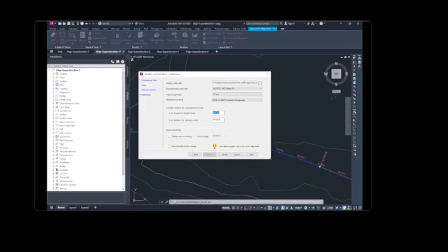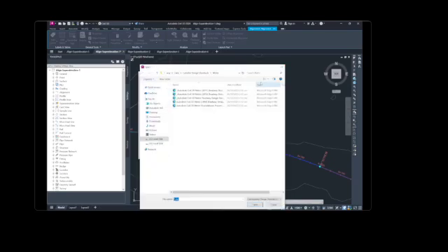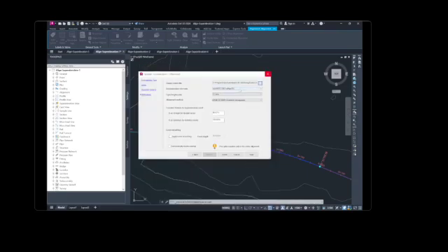In the design criteria file, select Autodesk Civil 3D Metric Roadway Design Standards, and the superelevation rate table AASHTO 2001, Emax 6%, transition lane table 2 lane, attainment method AASHTO 2001 Crown Roadway, transition into tangent 70%,